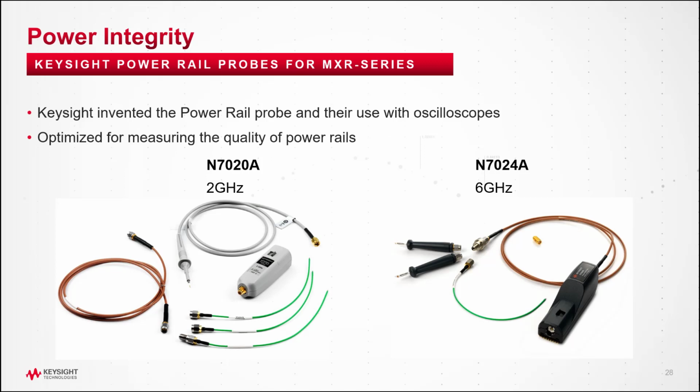Now, power rail probes is a very rich subject, and Keysight has many webinars and application notes on this, so I'm not going to dig into it too much there, other than to point out that Keysight invented the power rail probes and their use with oscilloscopes, and these probes are optimized for measuring power rail quality only. They're the lowest noise active probes around, but we're able to do that by just making them kind of a one-trick pony. They only measure power rails. So it's kind of the good and bad of it there.